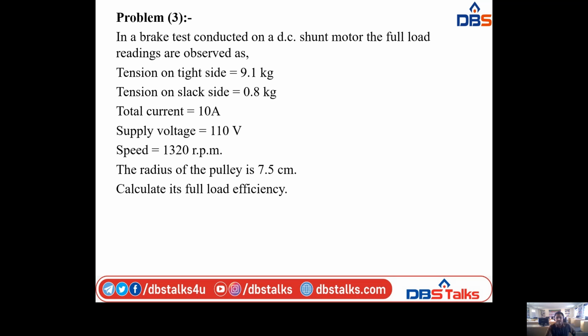So for the motor, they given that armature current is 40 amperes, armature voltage is 200 volts, the drop across its field winding is 15 volts, and for the generator, they given that armature current 32 amperes, armature voltage is 160 volts, the drop across its field winding is 15 volts, the resistance of each armature is 0.4 ohms.